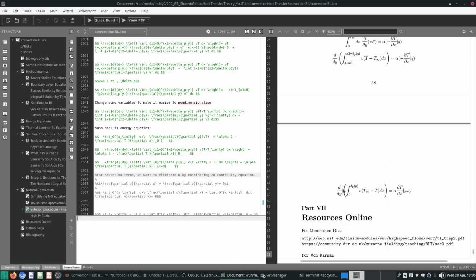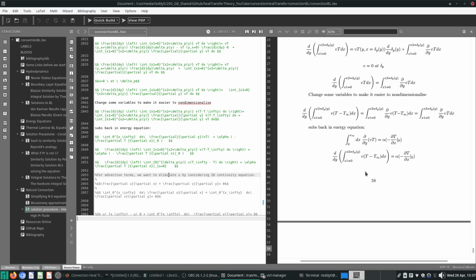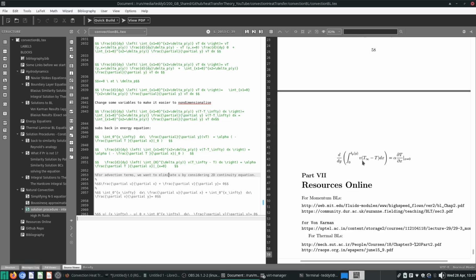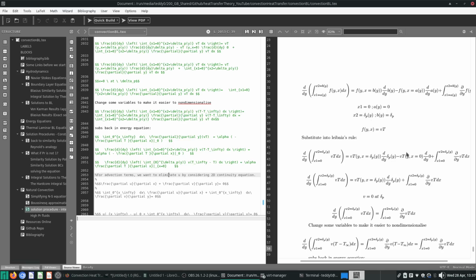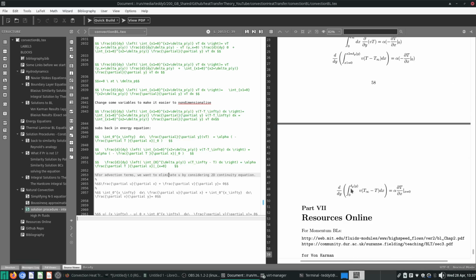So last time we left off, we developed our boundary layer equation for relatively high Prandtl number fluids. This is our energy equation for high Prandtl number fluids. Of course, the limit x2 here will depend on whether it's a high or low Prandtl number fluid. You can just swap it accordingly. But more or less, the form of the equation, no matter what the assumption is, will still look like this, except this limit here is changed.